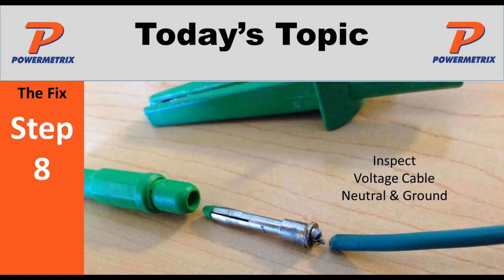And step 8, and this is a big one, is a broken ground connection on the voltage cables of a 7 or 5 series PowerMaster. What you want to do is, at the tip of that, it's like a little barrel nut. You can remove that barrel nut and inspect those ends to make sure they are soldered good or you haven't broken any wires or anything like that. But I would recommend inspecting your voltage cables for sure.